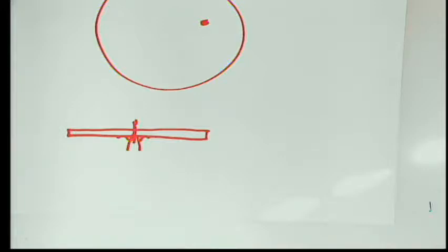Maybe some planetary gear systems in a car or something like this, but I can't really even think of a good example of something common that rotates non-centroidally, because the rotation is always much smoother if it's taken about that centroid. But in the event that it happens, the kinematic relationships let us think about the tangential acceleration and the normal acceleration of the center, and the kinematic relations are used to eliminate those from equations derived from D'Alembert's principle or from the method of dynamic equilibrium, F equals ma.